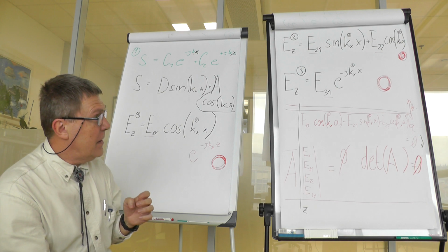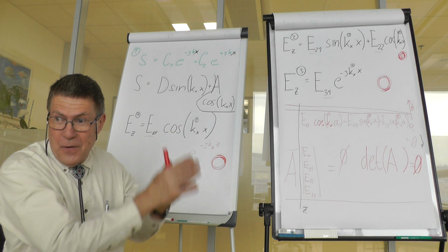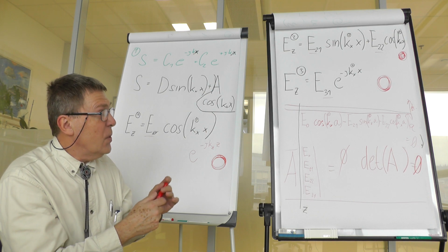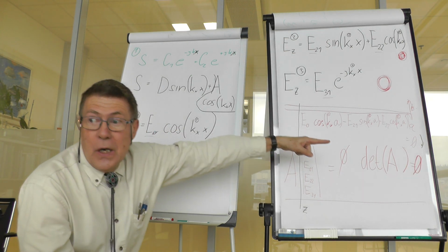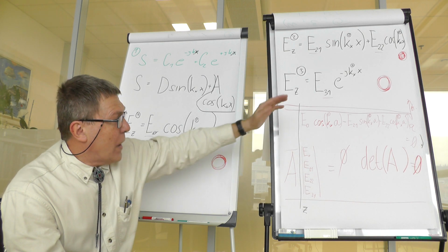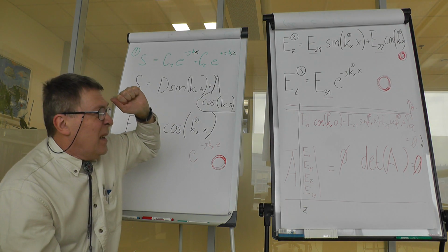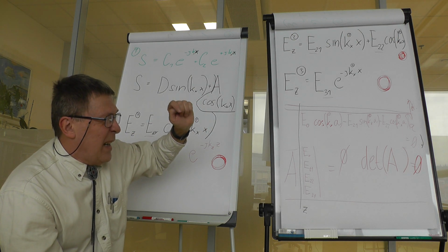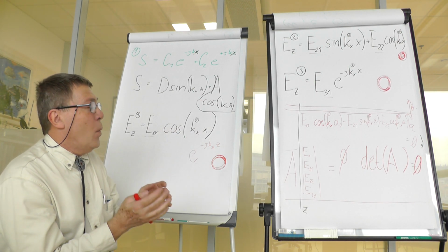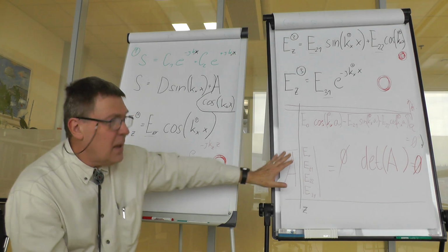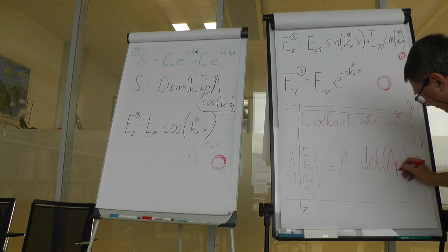We have, of course, something which we could vary, and that's frequency, but at a given frequency, we still do not know the value of the propagation constant along the axis Z. We can find out the case for any of the regions, and we have the formula on the table. But now we should find out whether there is any kx or kz which satisfies the condition of the zero determinant. So let's say that the A is dependent on kz.